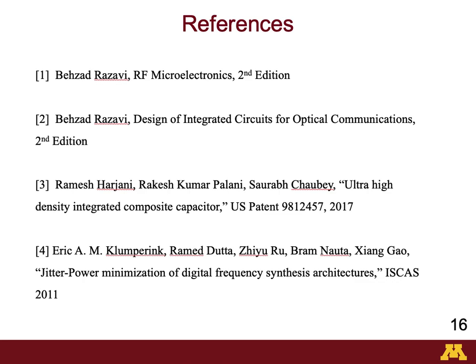So minimizing inductance and maximizing capacitance can be a target for the LC tank. However, if fixed capacitance is made much larger, then the varactor variation will have smaller impact on the VCO frequency tuning. So a trade-off definitely exists.